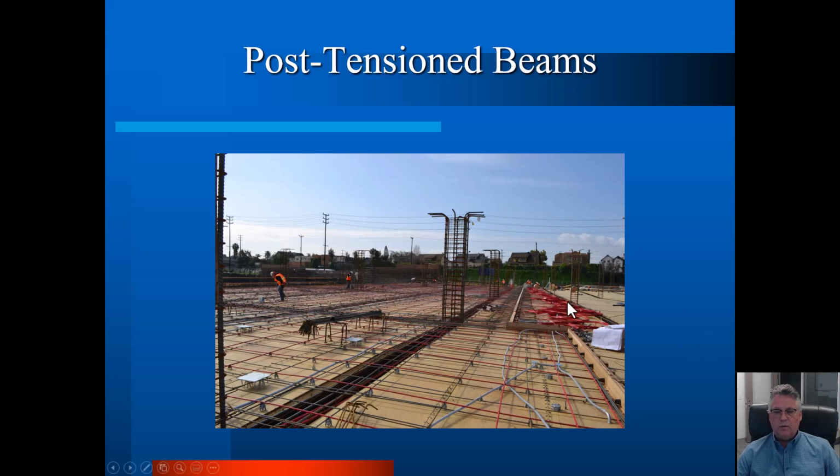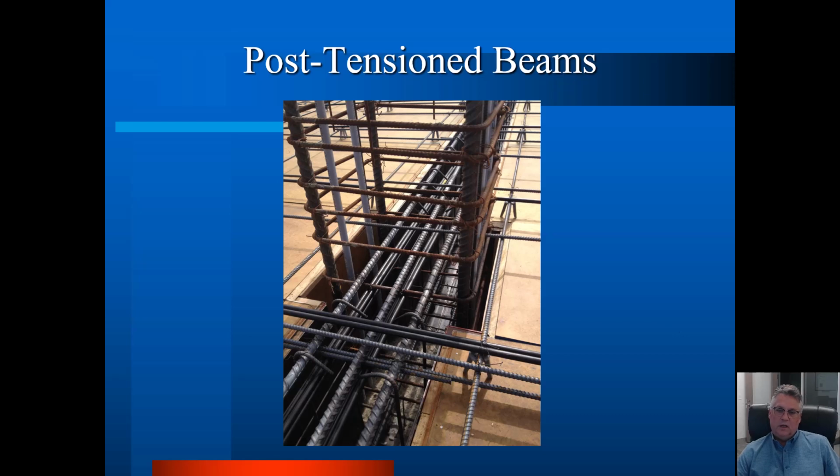Post-tension concrete, we will see that we can fabricate and unroll any length we want, 350 feet if we feel like it. Post-tensioning, one of the many, many benefits is that it effectively eliminates the lapping issue that also exists in reinforced concrete. So this is a close-up of a beam column joint.